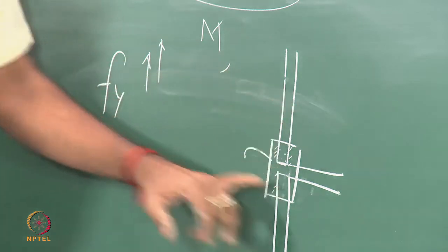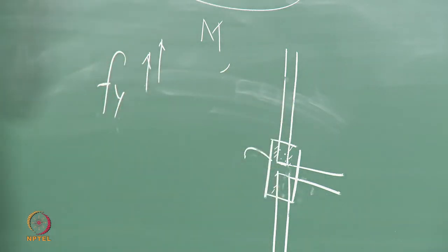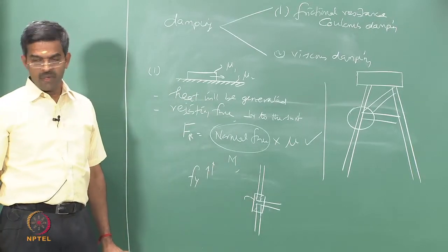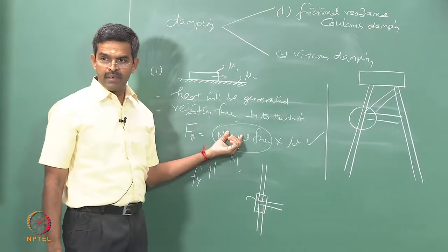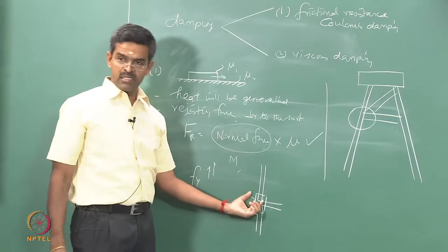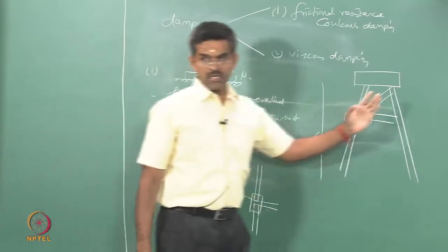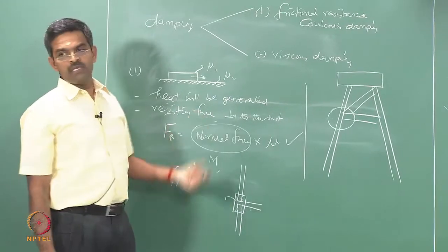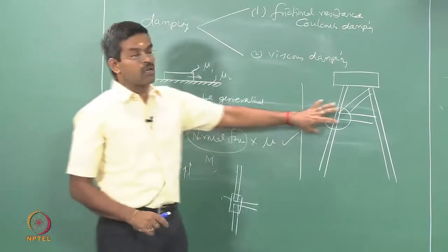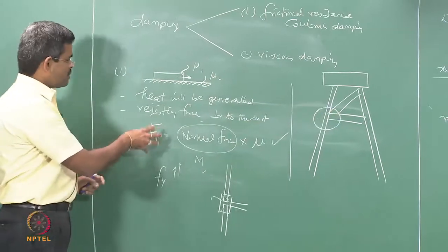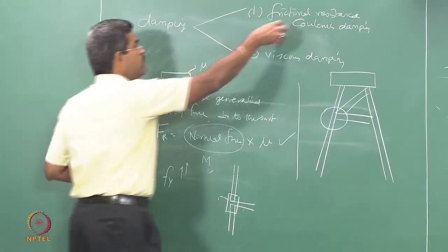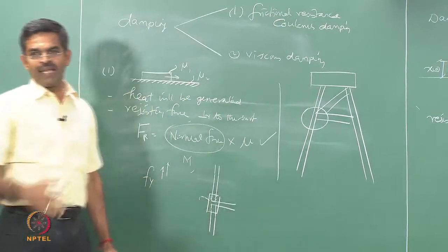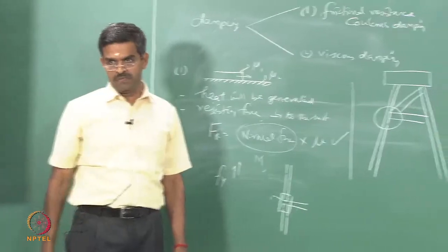When two materials of different yield strength grades are connected, when they rub against each other, they will offer resistance. So, this is a very valid example of the model applied in offshore structures where there are connections, but in new generation structures these connections are essentially avoided. Let us take for example a TLP. There is no rigid connection in a TLP of this order. So, this proposal of using Coulomb damping for expressing decay of response may not be valid for all kinds of structural models.